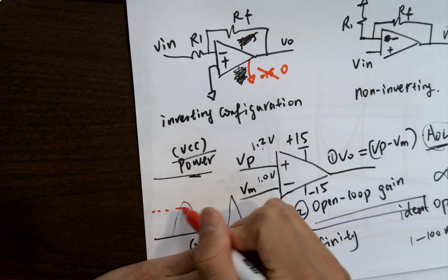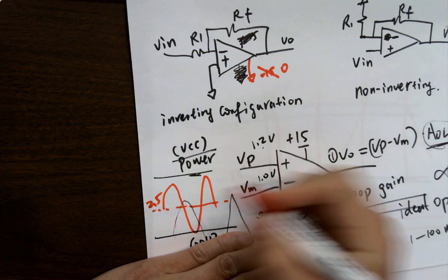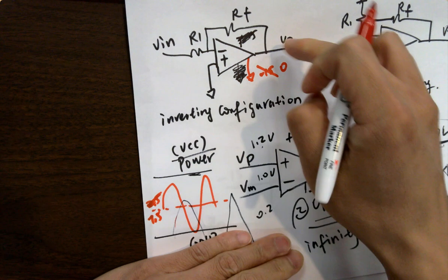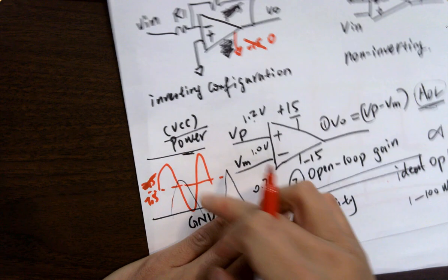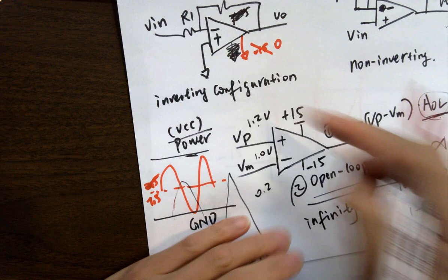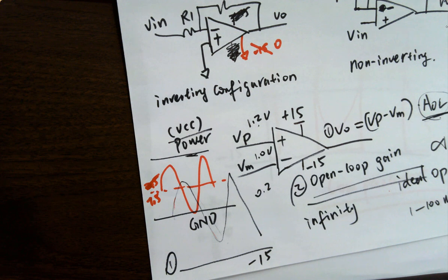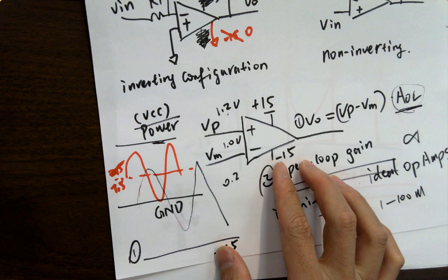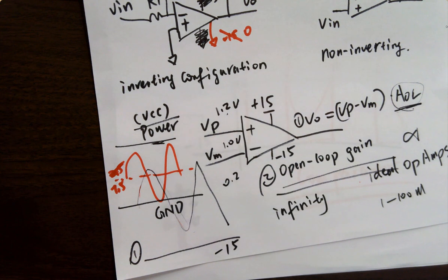So I have to provide a DC offset in the middle, so it's going to swing around that DC offset, called 2.5 volts, or let's say 7.5, because it's 15 volts. That's how we have to do it. But now, since we have negative 15, we don't have to worry about the DC offset. It's trying to simplify things for people who learn this for the first time, but it's actually not very practical, since usually we don't provide a negative voltage on the board. Its lowest voltage is just ground. We just have a common ground.